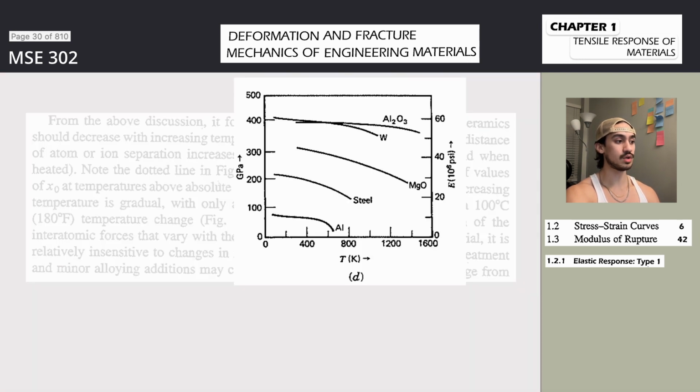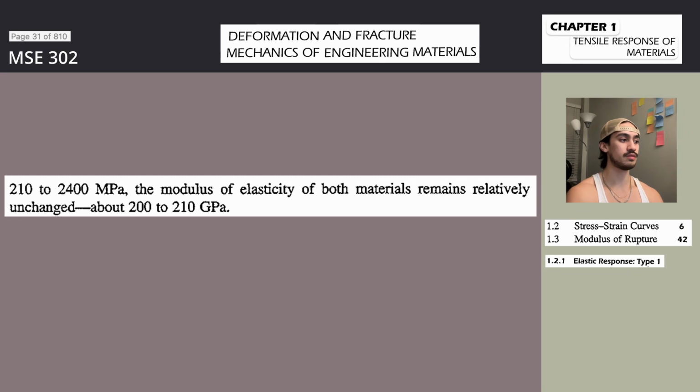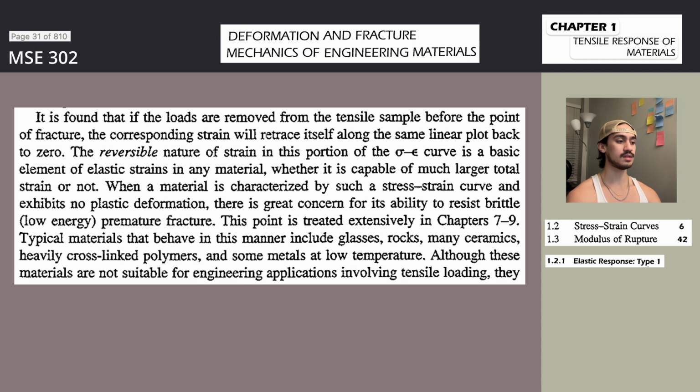For the case of tungsten and any other isotropic material, we have equation 1-15. If we compare equation 1-15 with equation 1-10, the elastic constants S sub ij may be described in terms of the familiar strength of materials elastic constants. Therefore, equation 1-16 a, b, c. Finally, from equation 1-16, we have the following expression, and we have equation 1-16b.